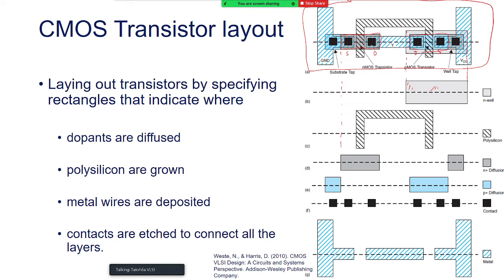You see now, this is the way I will create this, called the N diffusion area, N plus diffusion area, because this is where my NMOS transistor is fabricated. And now to isolate the source and the drain region, here is the poly mask that I have. So look at their position. When I have this poly mask right here, I already have the source and drain separated, and this is how the NMOS got fabricated right over here. Look, this poly crossed over that one. Okay, so this is basically a physical layout, the physical design of a CMOS inverter.